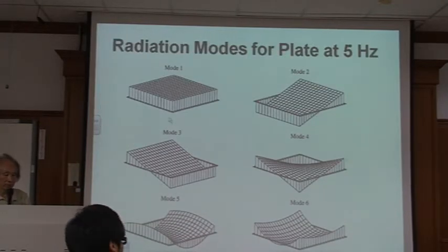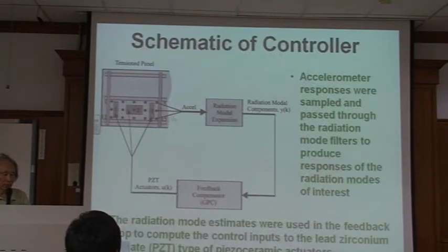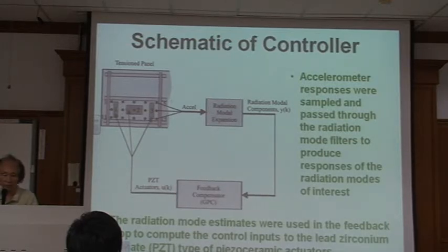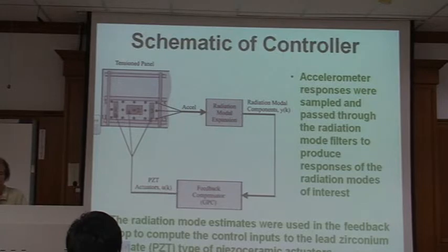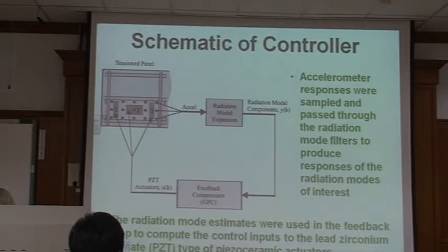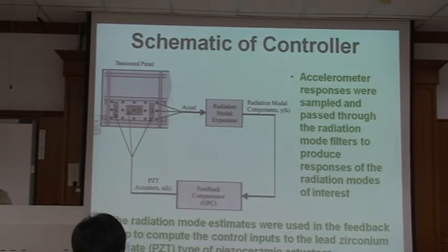And this is just the modes of the plate, just like the fuselage of the aircraft. The plate is just like the fuselage of the aircraft structures. So for that aircraft, we control the aircraft structural vibrations. That will reduce the noise, because all the noise inside the aircraft basically comes from the vibration of the fuselage induced by aerodynamics.